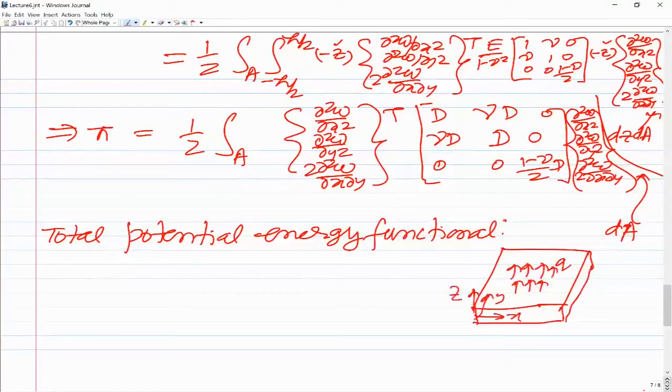And then on the boundaries, let us say we have the shear force term per unit length of course. So this is let us say Vn, n is normal. So depending on x face, y face, and negative x face and negative y face, you will have this Vn. And let us say we also have the moment. So the moment is let us say this is the moment Mn. So this moment here is about the y axis. So let us say this is Mn, and this Vn and Mn are there on all the four boundaries.